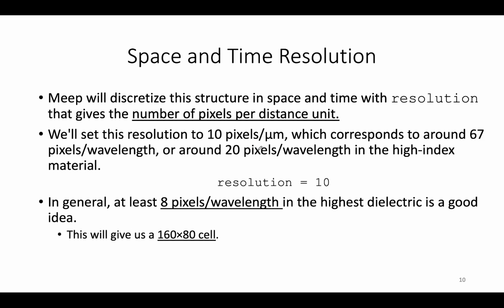So let's talk a little bit about discretization in space and in time. MEEP deals with resolution in time and space by introducing the resolution. So MEEP will discretize the space using the resolution variable that gives the number of pixels per unit distance.